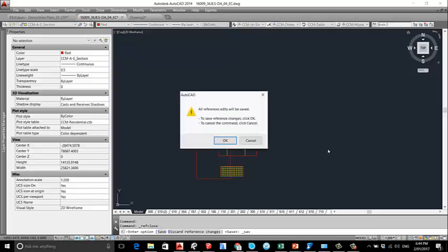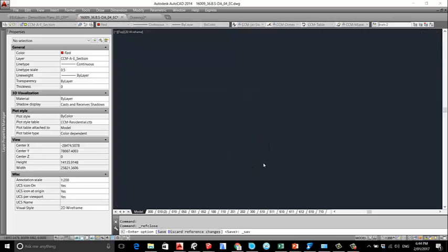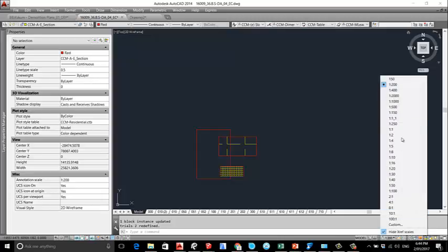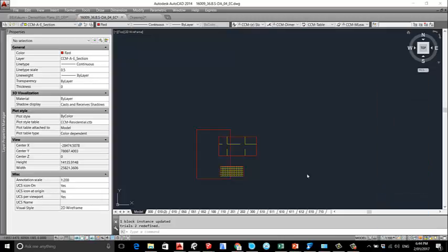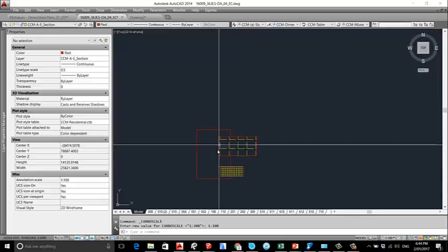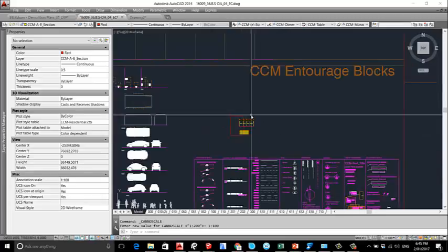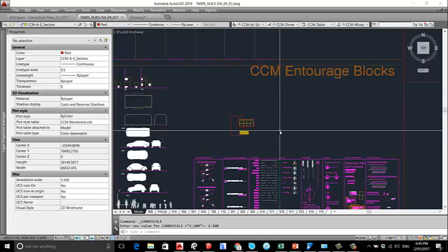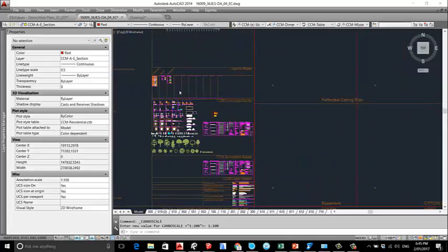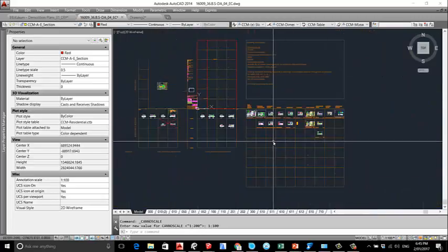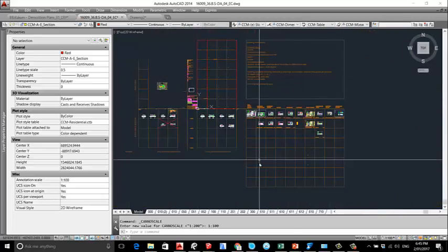So we just save this block, okay. And if we change the scale 1:100, the block doesn't change, the hatch changes, but this that we said is not to change, it doesn't change. So this is very important to have clear, because it gives a lot of power of maneuver with the same drawing in different scales. And the idea is that the fewer lines we have in the drawing, the better. Okay, thank you. Bye.